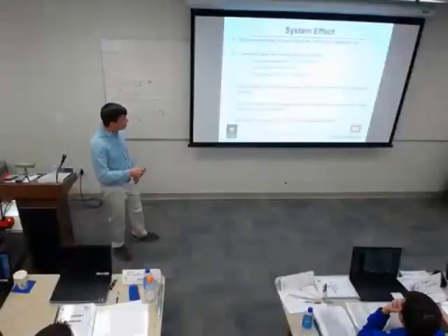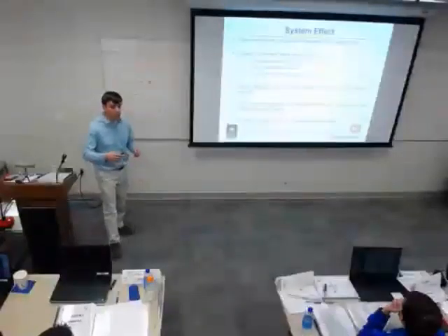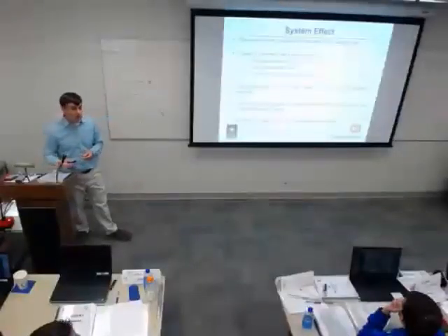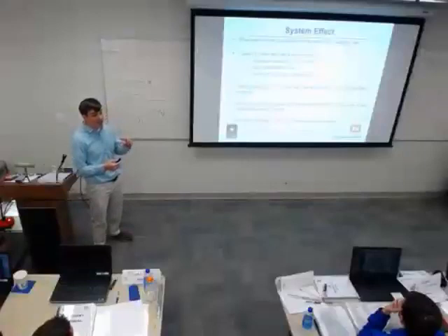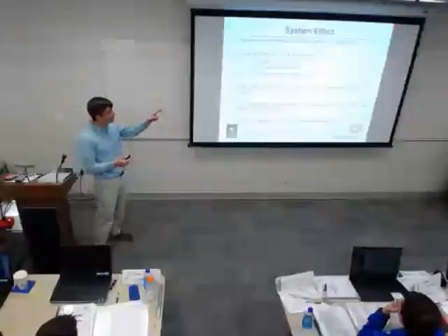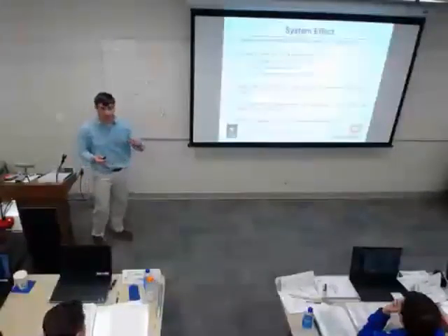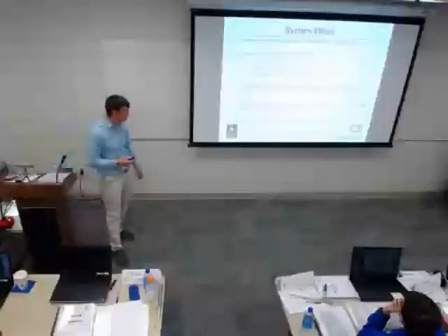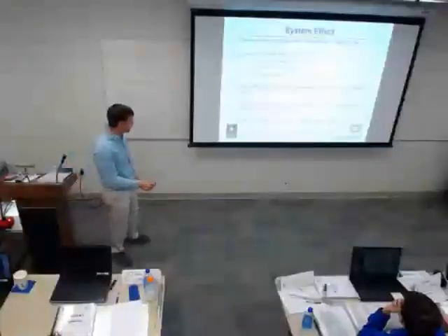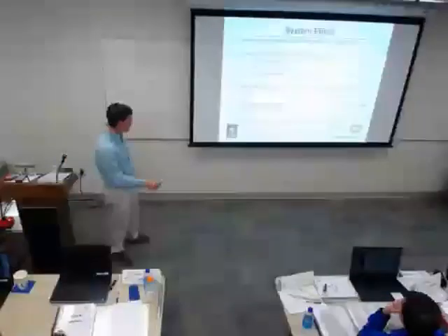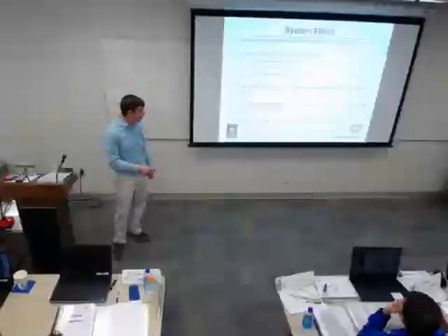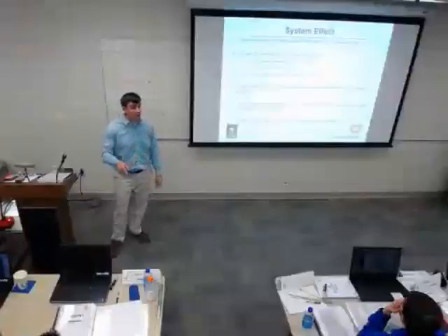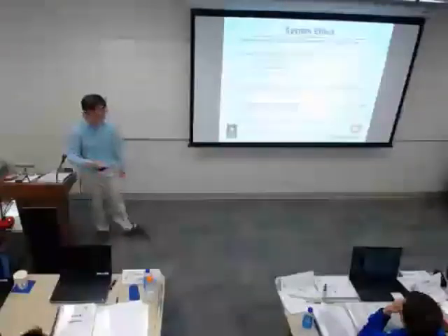The designer should be looking at if he's going to have system effect and accounting for that in his equipment schedule in the means of added static pressure. The end result of evaluating system effect is, do I need to plug in a number to account for some extra resistance? And this standard can tell you much more about it than I ever could. If you really want to dig into this, AMCA 201, that one's also available on IHS.